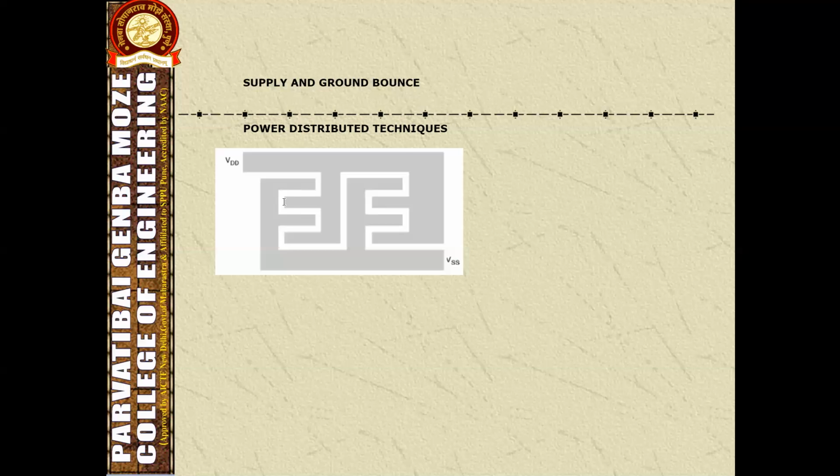Here, one thing we use is a decoupling capacitor. In order to reduce the power supply noise, capacitors across the power supply pins are used in printed circuit board design. Further, in large integrated circuits, decoupling capacitors are used in the semiconductor chips. Therefore, in microprocessor integrated circuits, to add decoupling capacitance, a separate chip is mounted on top of the integrated circuit.